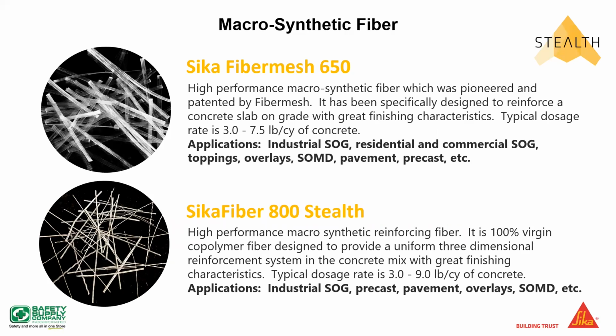Your typical dosage rates are your 3s, 4s, and 5s, and 7.5 is actually a very common one. I've done projects recently with the 800 Stealth at 7.5 pounds of fiber per yard of concrete, and I did a project with 8 pounds of fiber per yard of concrete.